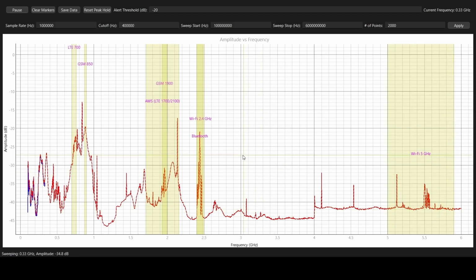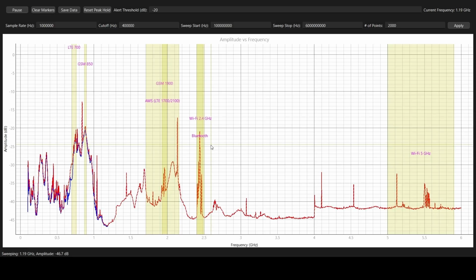Okay, I don't want to make this video very long. I'm trying to divide the information that we can gather from this spectrum analyzer into separate videos. We are going to look at different details in separate videos to not make every video very long. But just one last thing I want to show is I want to change the frequency span to just look at this range to see if I can, with some good accuracy and frequency resolution, see the OFDM modulated Wi-Fi.